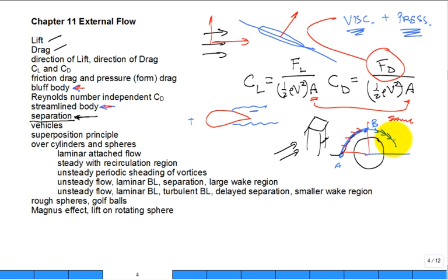Okay? But then you come around on the back side in this quadrant, and what's happening to the pressure? Well, it's trying to increase. And what about the speed? Going down. That's an adverse pressure gradient. You're going into a higher region of pressure. It doesn't like it. It can do it. It's called a diffuser, but it's challenging.